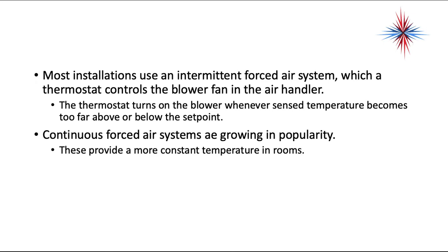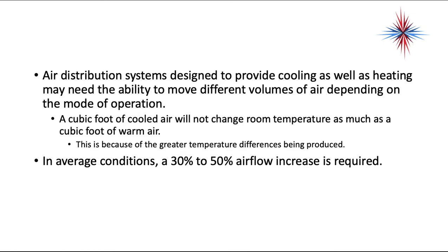Continuous forced air systems are also growing in popularity. They provide a more constant temperature in the rooms. The difference is that in continuous forced air systems, the fan runs constantly. Air distribution systems are designed to provide cooling as well as heating, and they may need the ability to move different volumes of air depending on the mode of operation.